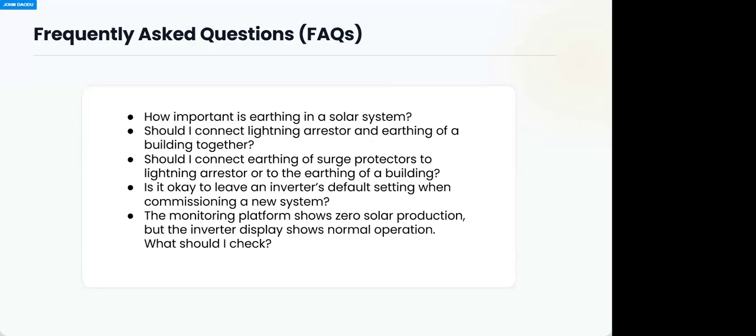But if you have not done the common connection, your inverter is in trouble, because you have a voltage between the neutrals that's high. You can have as high as that 240 between the two neutral input and neutral output, when it's supposed to be the same thing. So that can pose danger to the system.